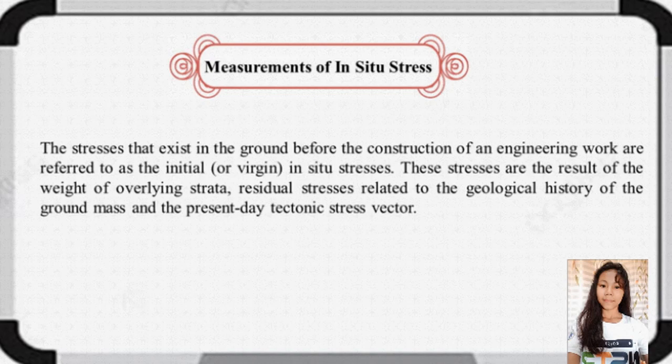Most in situ stress measurements are undertaken in rock and involve fixing a strain measuring device in a borehole and overcoring the device, which then records strains opposite to the stresses existing in situ. The device has mostly to be calibrated in the laboratory in a block of rock taken from the test site. Stress may be measured two-dimensionally by fastening a strain measuring device at the bottom of a borehole and then overcoring.